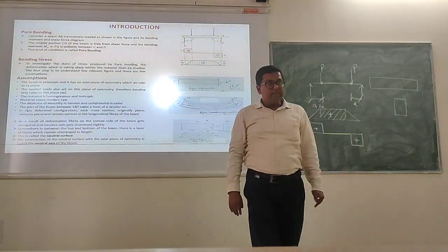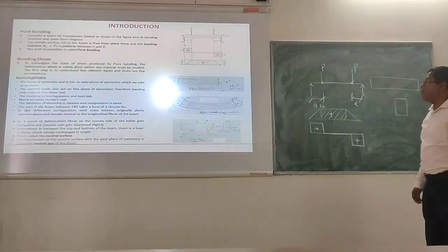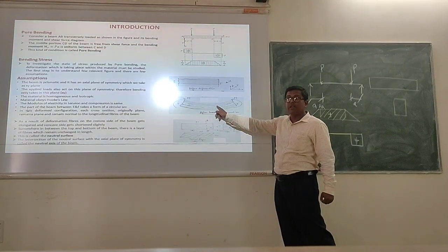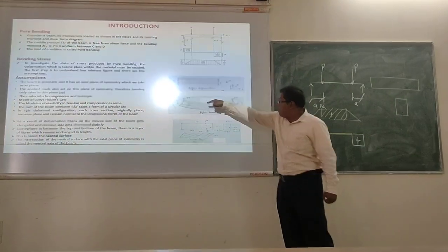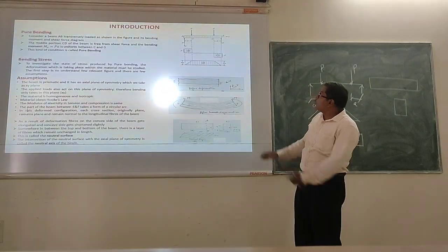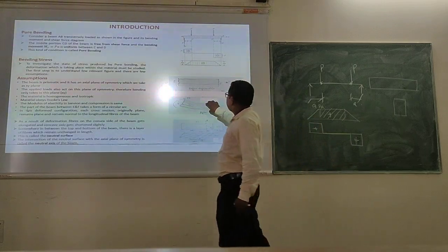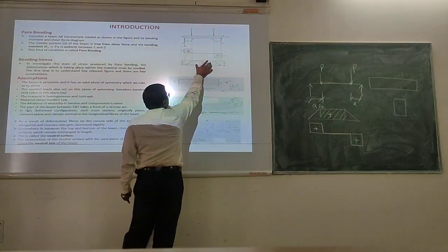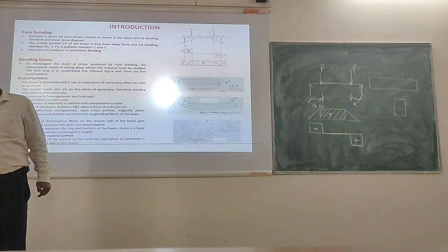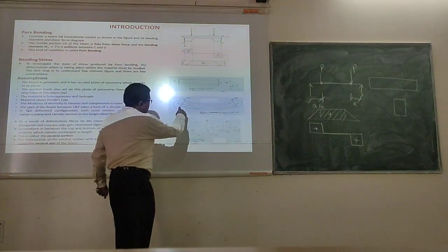Now, when this loading condition comes into the beam, so now if I load this beam with this PB load, and if I investigate that beam, what will happen? After the deformation, it takes the shape something like this. So there will be a bending kind of thing coming in. Correct? So where will this phenomenon occur? Predominantly this phenomenon will come in between this portion. This is under pure bending. Correct? So there is a downward bending.